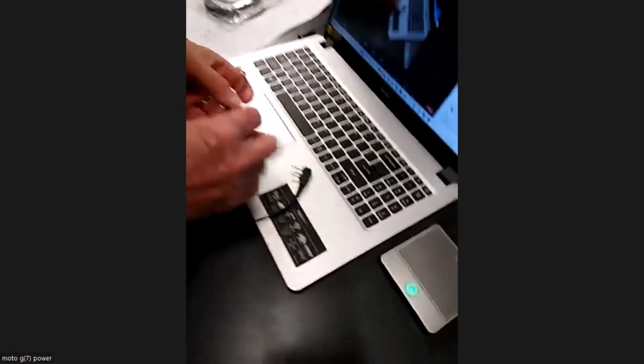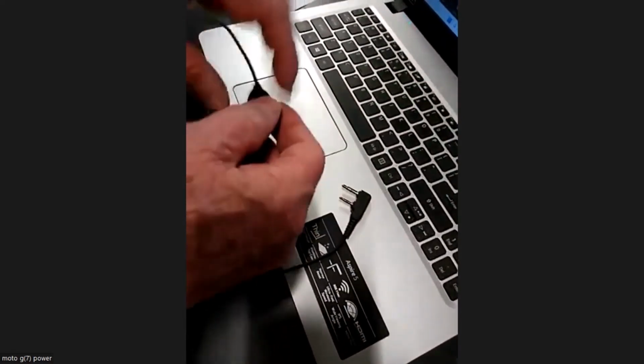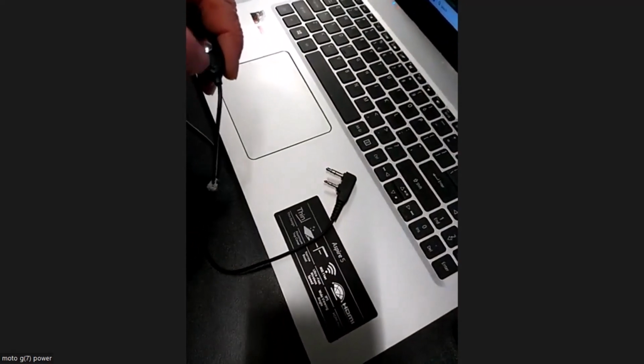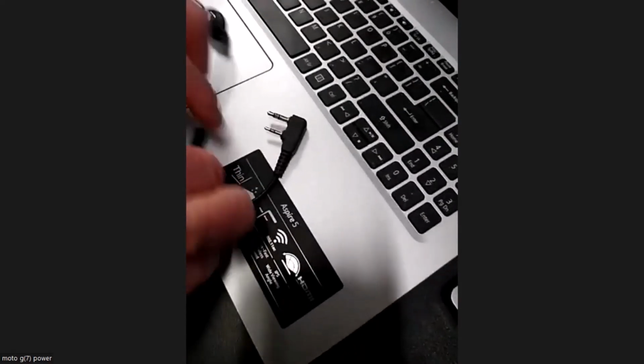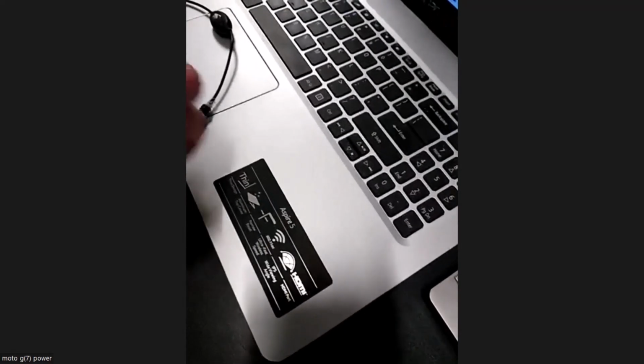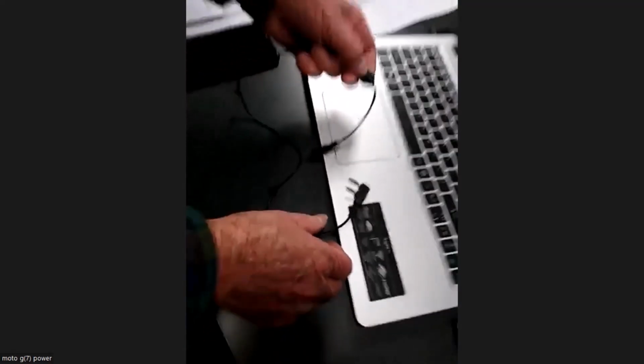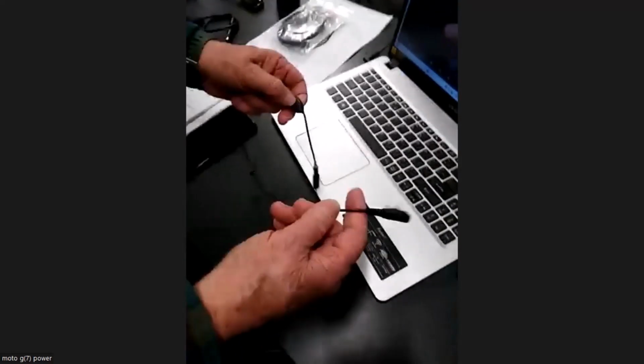This is what I was kind of speculating. I did not order yet. I'm going to. Since I have 3 Digi-Pis, I took an earpiece, the earpiece that came with the Baofeng, and I opened this up and took the mic out and bypassed everything except the PTT, putting this across the PTT and ground so that I can plug this into a radio and just key this to make sure that it's going to key it.